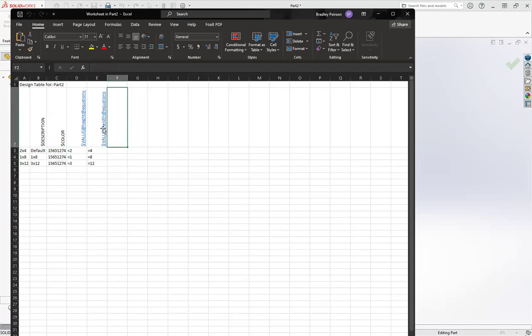And for our purposes, one of the biggest benefits is we can change the value of those variables so that we can have different dimensions, different features in different configurations. And every time we want to change an actual global variable, it's $ value at the variable name at equations, and it always maintains that same format.